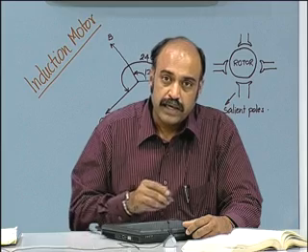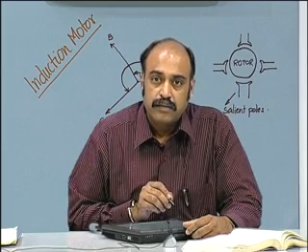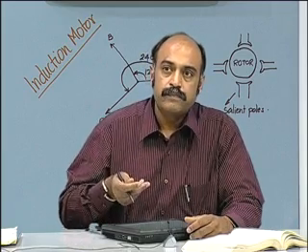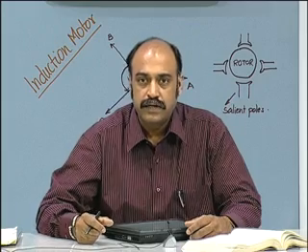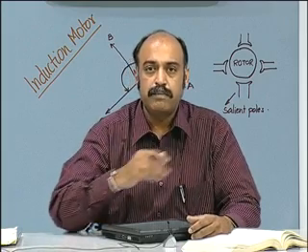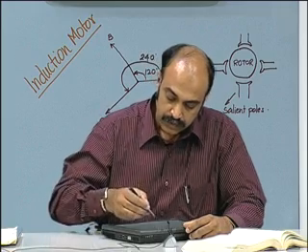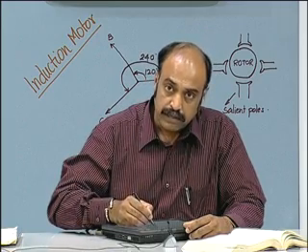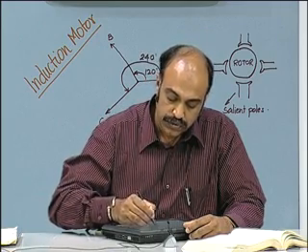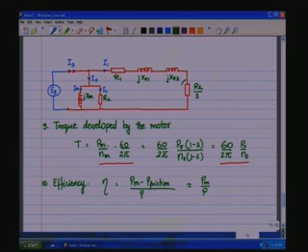So R2 by S becomes negative, which means the polarity is reversed, which means now that it is pumping energy back into the mains. So it will look like that because the slip becomes negative, this becomes a source. This portion would become a source in the case of induction generator. The polarity would reverse and then starts pumping energy back into the mains.